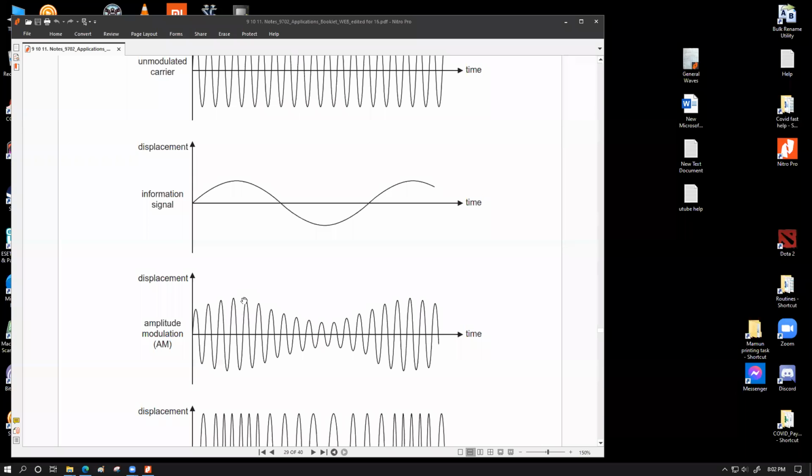Now, the point I'm going to make: whenever we assign a different radio station, a different transmission station, a different carrier frequency, they will operate at that specific carrier frequency, and as a result, they will not interfere with each other's signal, because to have interference or superposition, we need multiple waves to have the same frequency. In this case, we are precisely avoiding that phenomenon.